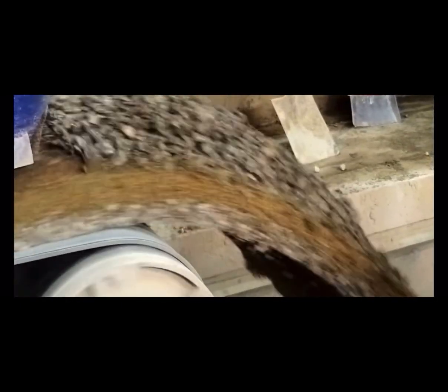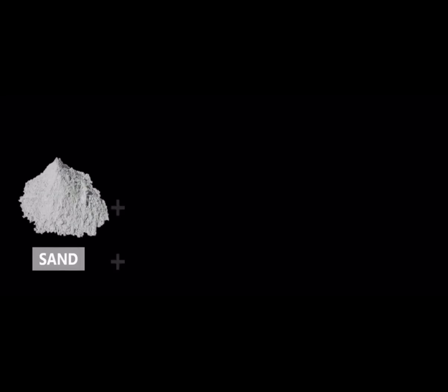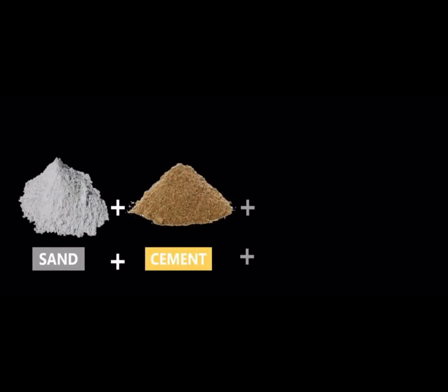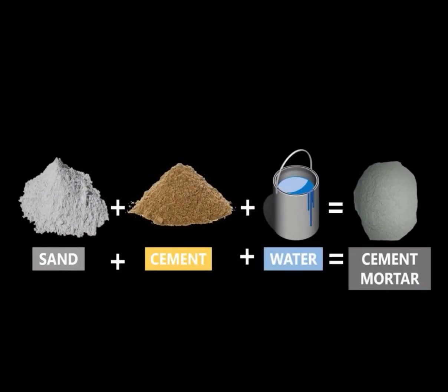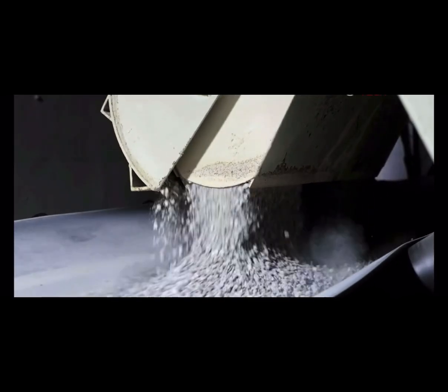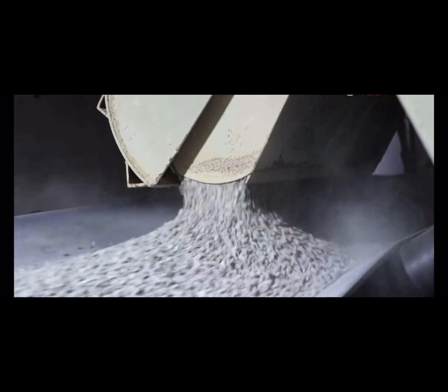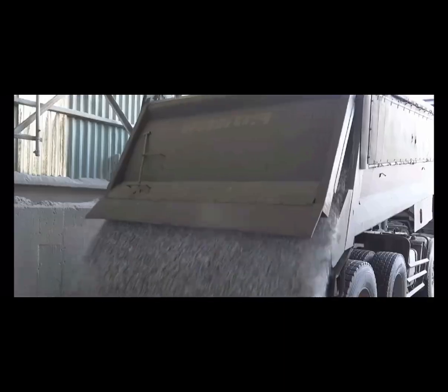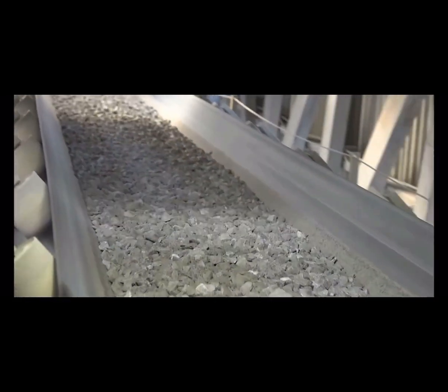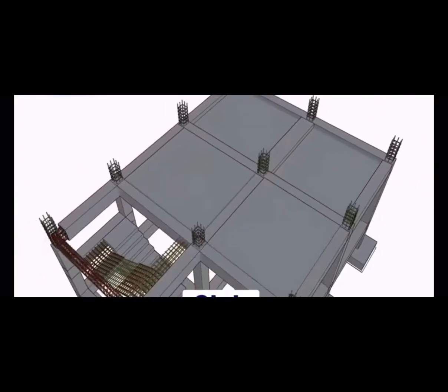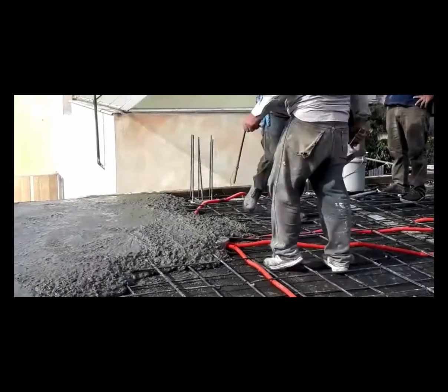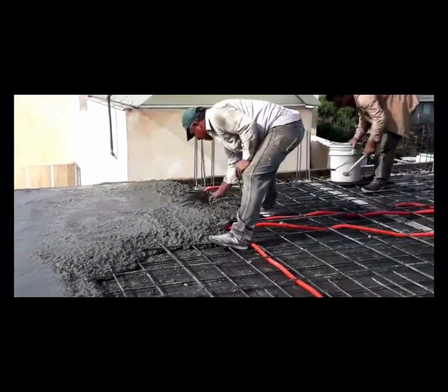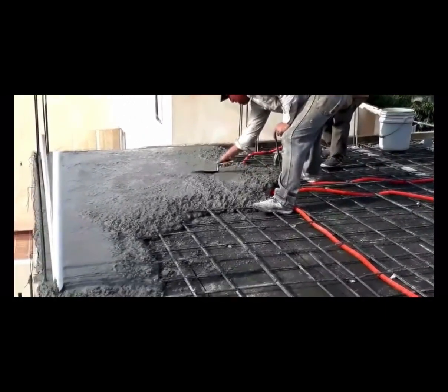The first step is to measure the proportions of cement, aggregate, admixtures, and water based on the desired strength and characteristics of the concrete. In fact, concrete mix design is an entirely different discipline dedicated to finding out the right proportions of raw materials in order to reach a target tensile strength. Moreover, building codes have been developed that specify the ratio of cement, aggregate, and water based on the different types of construction. The next step is to mix the ingredients thoroughly to create a uniform mixture.